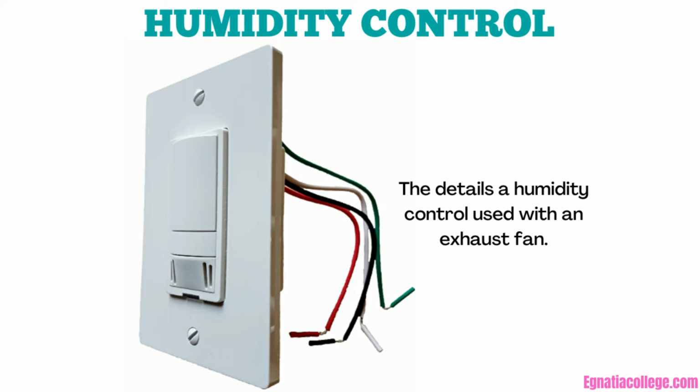The comfort level is about 50% relative humidity. Adjustable settings are from 0 to 90% relative humidity. The electrician must check the maximum current and voltage ratings of the humidistat before the device is installed. Some humidistats are extra low voltage devices and require a relay. Other humidistats are rated at line voltage and can be used to switch the motor directly. A relay is not required.